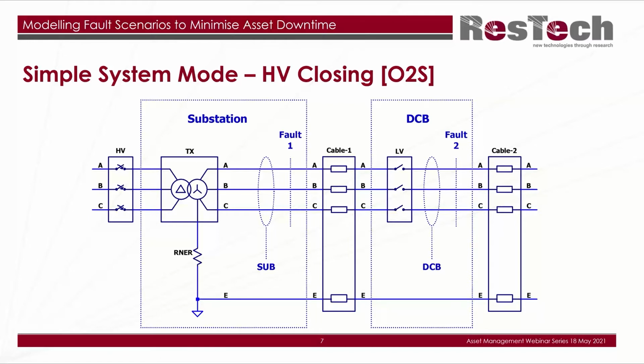So you can imagine this particular mode of operation as we energize. If there was a fault, for example, in the substation before the open DCB contactor, that would actually reveal a fault, because it would basically be closing onto a fault. And this is why we want to consider the modes where things are turning on. Now, the next mode after this would be when the actual